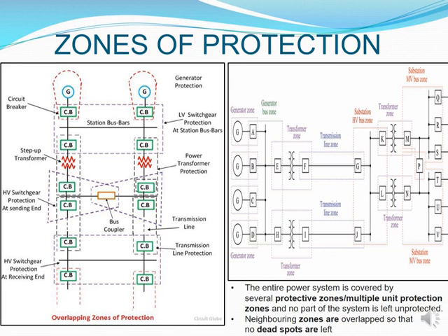You can see that on either side, top and bottom of the transformers, you've got circuit breakers that are looking out for those transformers. And this system keeps on sharing the circuit breakers, because the same circuit breakers that are on top were the ones at the bottom looking after the station bus bars. They also look at the transformers and protect those transformers. So again, if you had a fault on one of the transformers, then both its circuit breakers would open and that fault would therefore be isolated from the system.